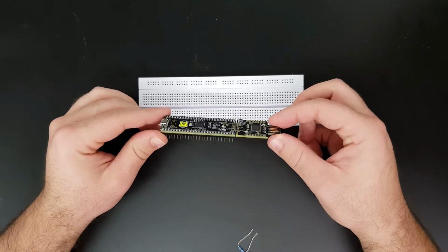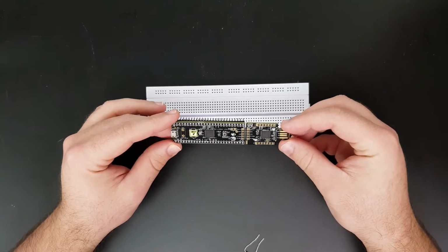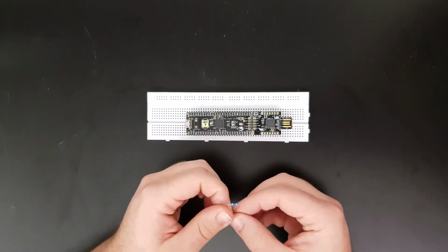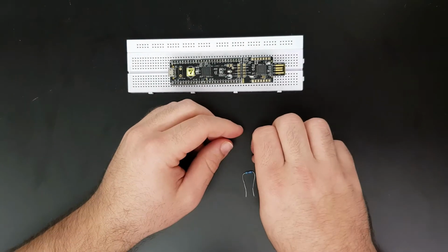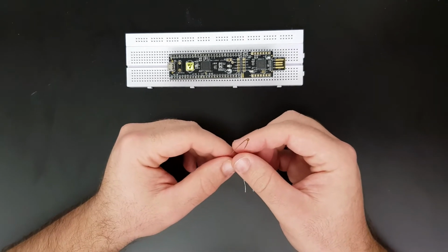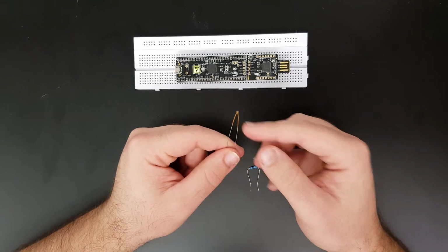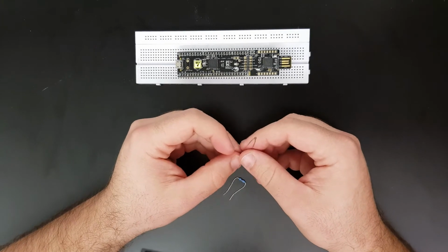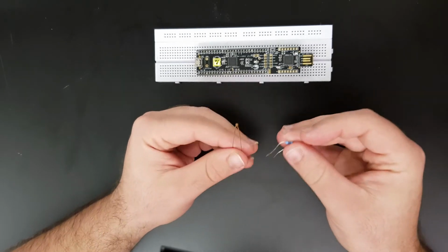This is basically our main controller, microcontroller that we are going to use for all the projects in this lab. And here are the devices that you're going to use specifically for this one. This is a 10K ohm resistor. This is a thermistor. The thermistor is a device that changes its resistance according to the temperature. Specifically, this thermistor, whenever the temperature increases, its resistance drops. And you're going to develop a way to measure the temperature using a voltage divider composed by a resistor and a thermistor.